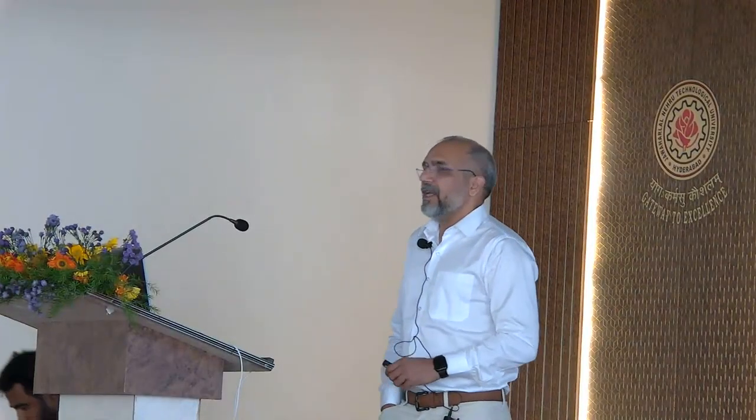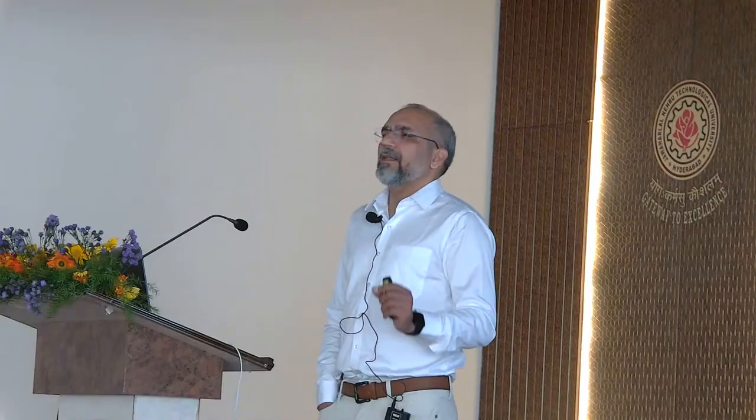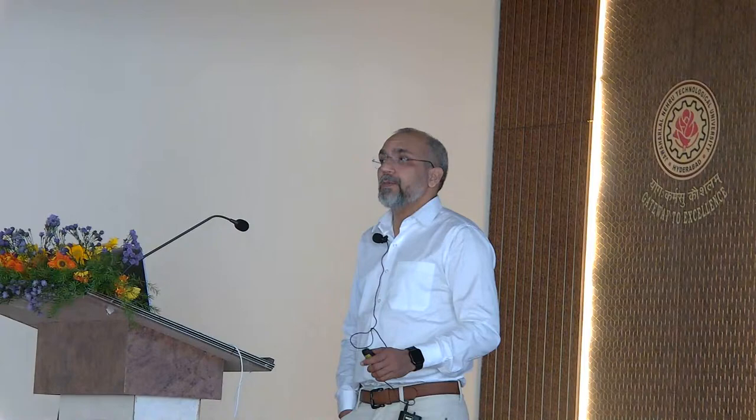When we talk about physical vapor deposition, there are different subcategories like sputter deposition, electron beam deposition, thermal evaporation deposition, arc evaporation, or pulse laser deposition. Each of these PVD methods is similar in terms of working mechanism, but they have a different procedure. When I say different procedure, the way they evaporate these molecules, that technique is different. Otherwise, the mechanism is the same.